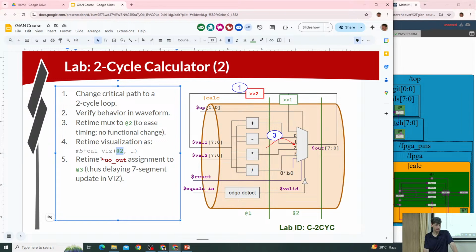Also, we currently have the inputs and the outputs all coming from, I think it's stage 1. Let's change the output hookup with the 7-segment display logic. Let's change all that 7-segment display logic, which is fed from out, now to stage 3. I think it's all currently jammed into stage 1. Let's stretch this out, give it its own cycle now after our stage 2 logic.